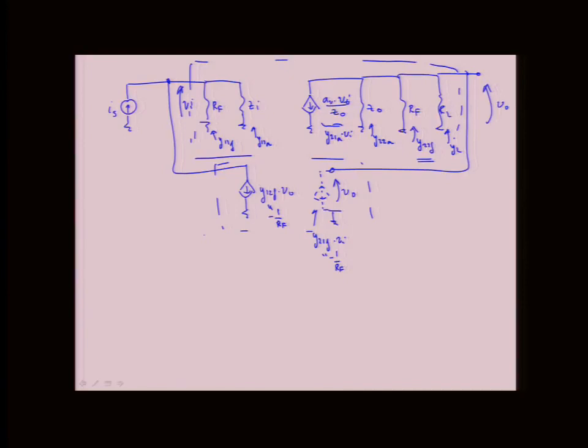It's the same as the shunt that we originally looked at, and I can also just go ahead and really de-embed A and F from this piece, right? So this is the feedback current, and I can say that for A, I'm looking for A that forms closed loop as A over 1 plus AF, right? So A will be, for I feedback equals 0, what's the forward gain?